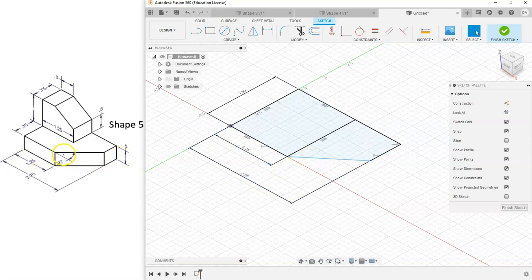Well, it tells us an angle. Well, okay, and you might be thinking to yourself, well, Mr. Anderson, I don't know how to put down an angle. Well, it's actually pretty straightforward. Let's grab our dimension tool and we can learn. If you look, it's an angle between this line and this line. So I'm just going to use my dimension tool and select those two lines and drag it in the correct direction and type in 45. And since these two lines are not parallel to each other, it automatically makes it an angle. It's automatically measured in degrees. And that's essentially how angle dimensions work.